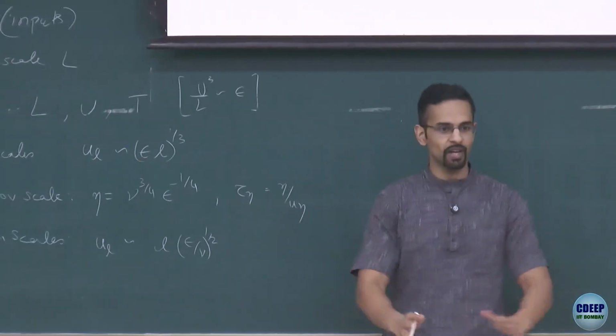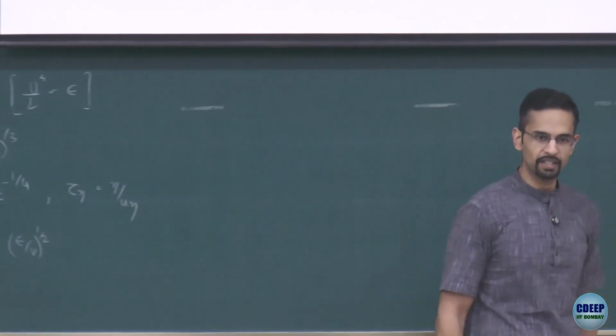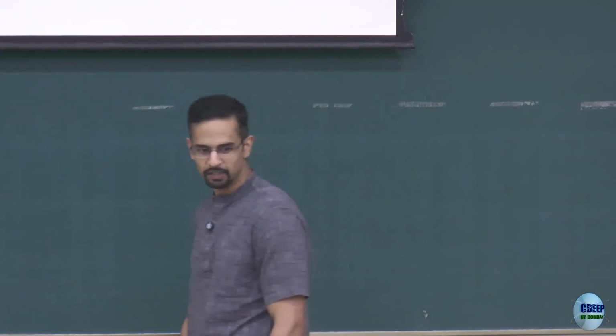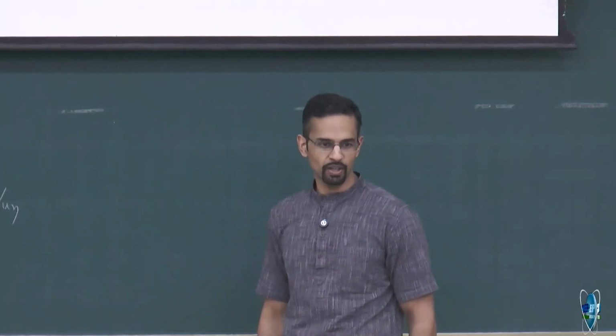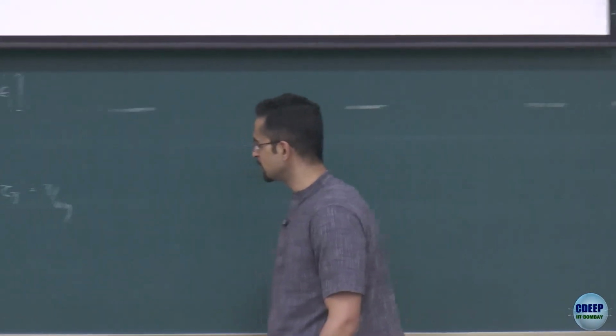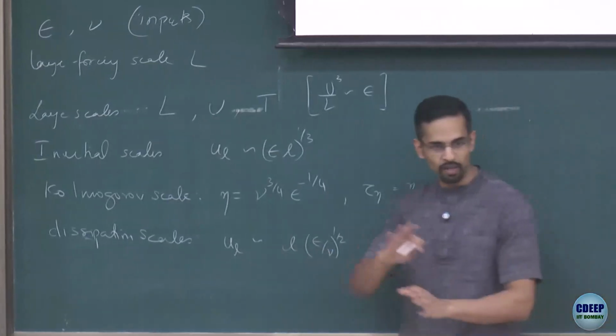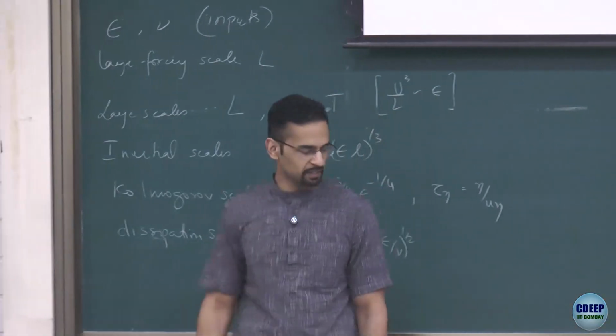Because if I try to calculate derivatives only looking at the filtered large scales, it will look like there are discontinuities and jumps. And that's why the turbulent flow looks so chaotic and rough in space. Okay, so this is the overall picture of how the flow field varies, how it is multi-scale.